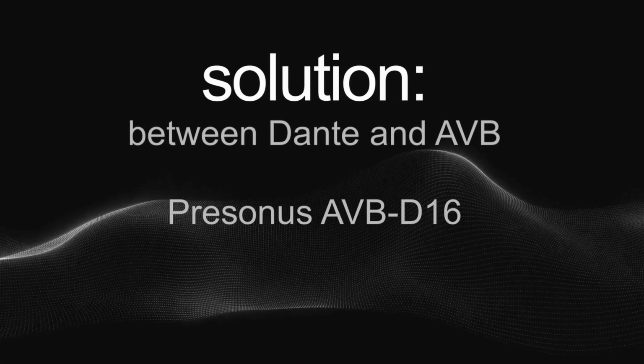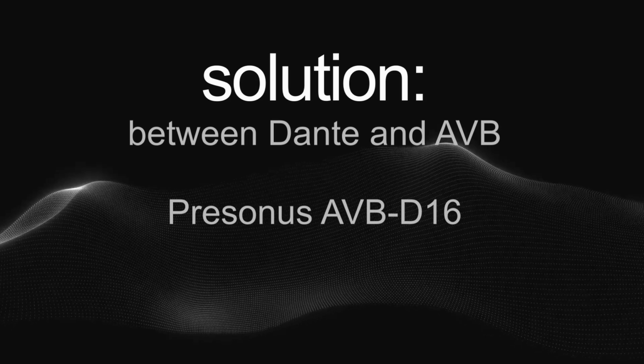So what ended up being the solution between Dante and AVB? The solution that I found for connecting Dante to AVB was the PreSonus AVB D16, a straightforward converter that takes up to 16 Dante channels and turns them into AVB audio streams. As soon as it gets audio routed by Dante Controller, it creates AVB streams that appear in the network for other devices to subscribe to. It also uses built-in sample rate conversion to keep things synced, even if Dante and AVB run at different rates, like one could be running at 96 and the other one could be running at 48.